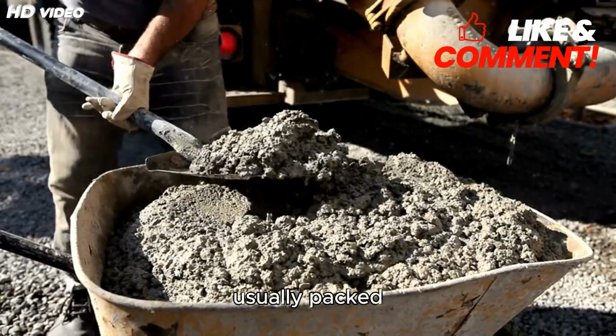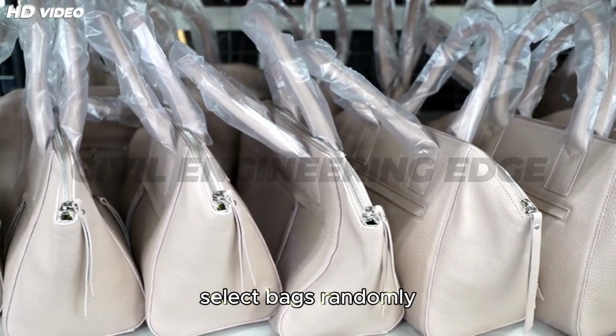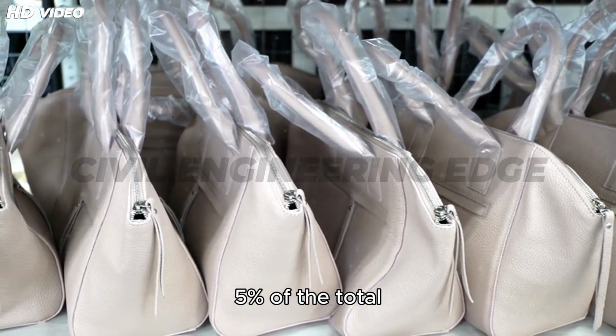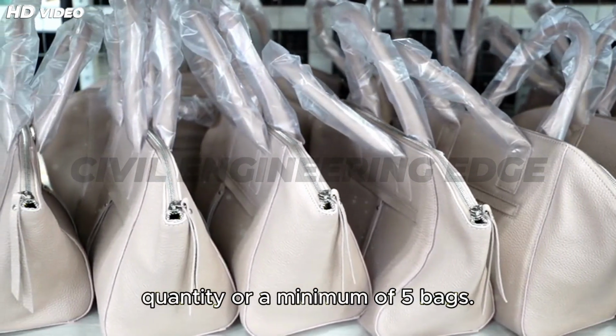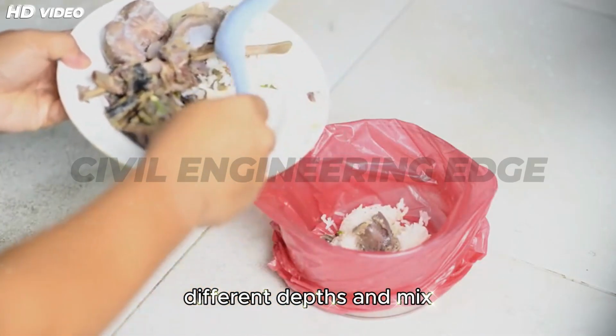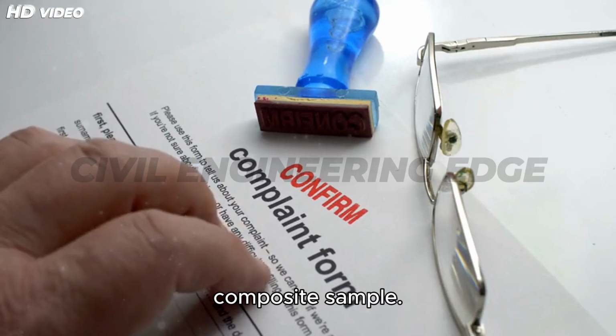Cement is usually packed in 50 kilogram bags. To take a sample, select bags randomly across the consignment, typically 5% of the total quantity or a minimum of 5 bags. Open each selected bag and take two scoops from different depths and mix thoroughly in a clean, dry container. This forms a composite sample.